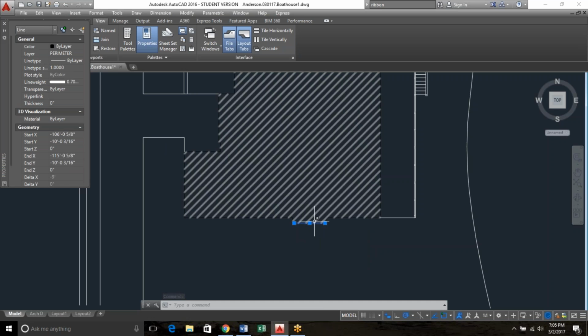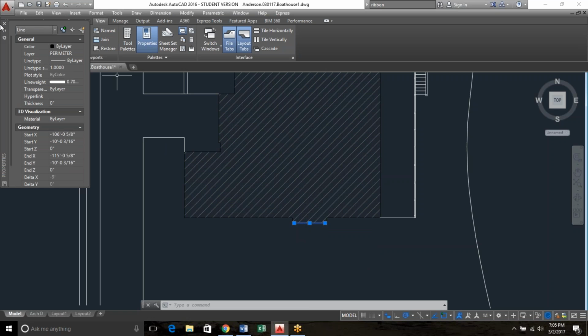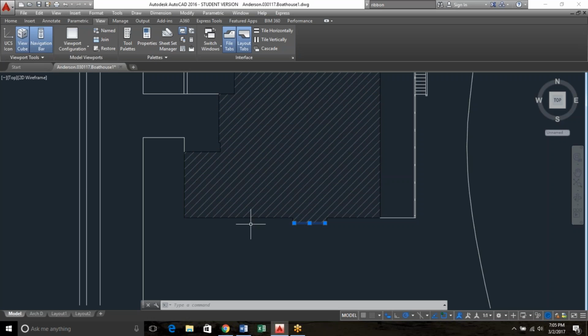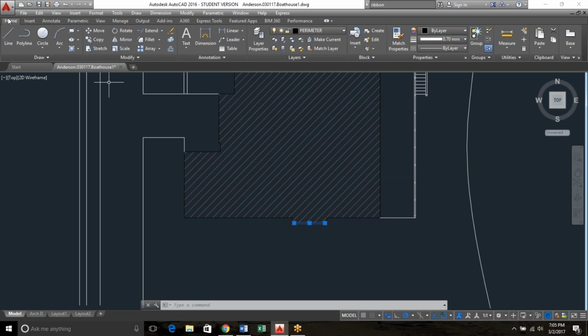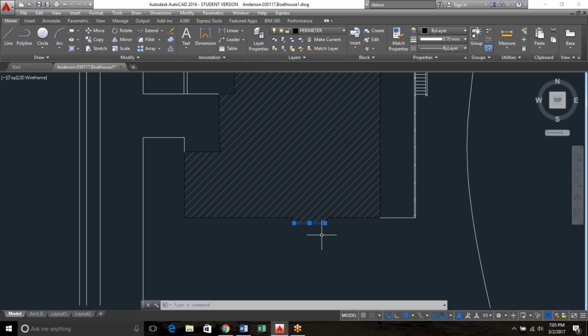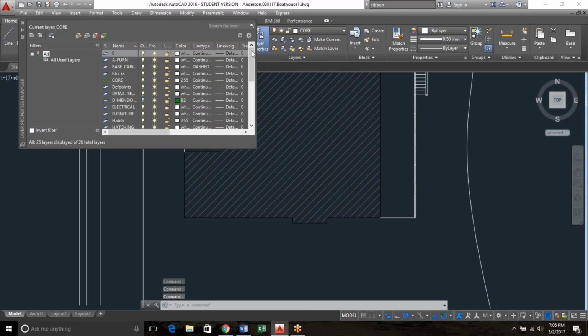Okay. So now the other way. On this, you showed me how to do it here. Is there another way to change that thickness as well? What's the other way? So close out of that little properties bar that you have open on the left and go to home just so I can get my bearings right again. And then if you have the line selected right now, click on layer properties and open that up.